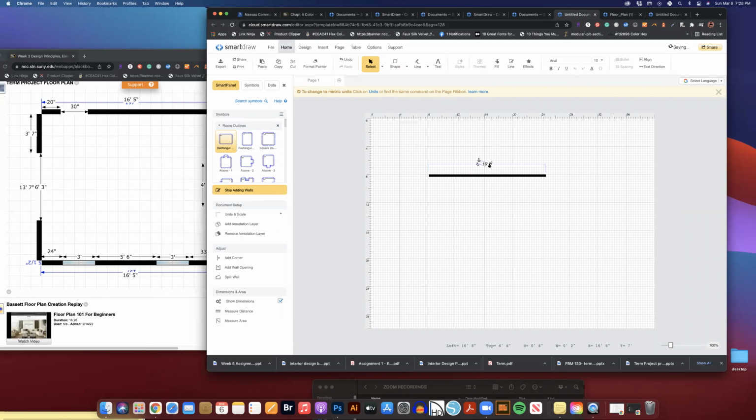Oops. If you click down like that, it's okay. Just click undo. Or you can delete it if I get my select tool. So you can delete it with the select tool if you did that. So now I'm clicking on this line again with my select tool. Click, and then I'm going to change this measurement to 5 inches because it's 16 feet, 5 inches. So that will give me that first line.